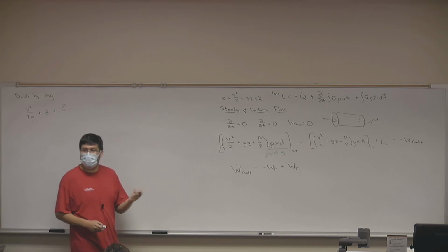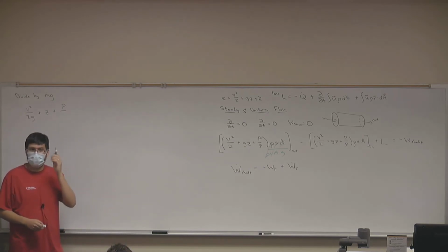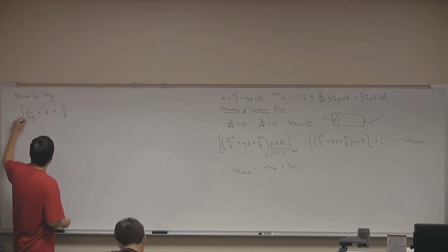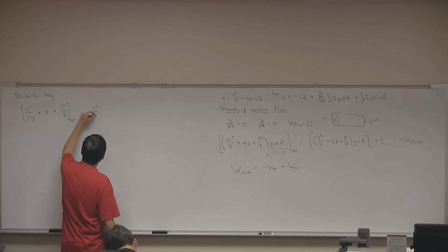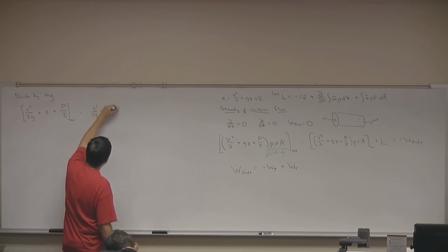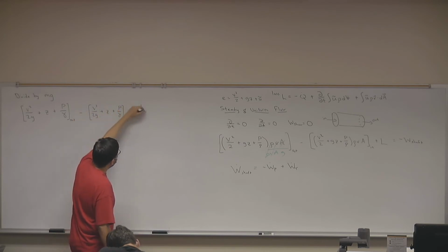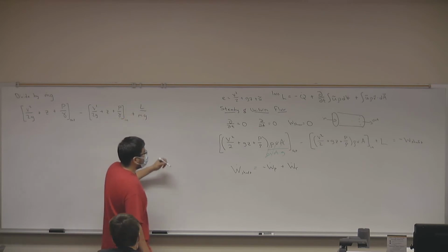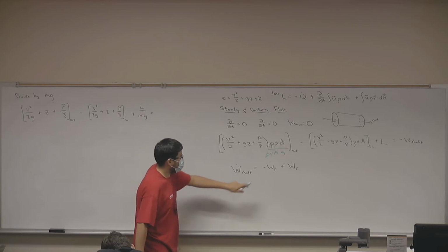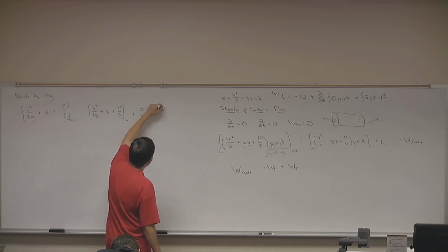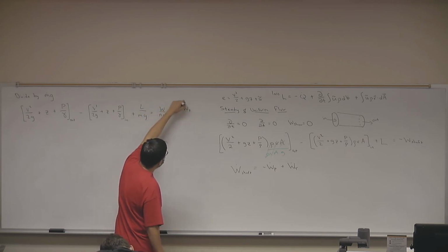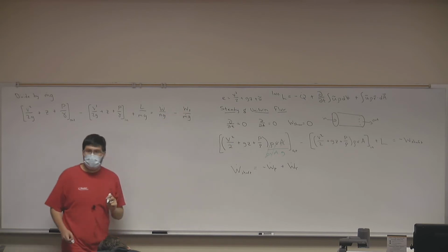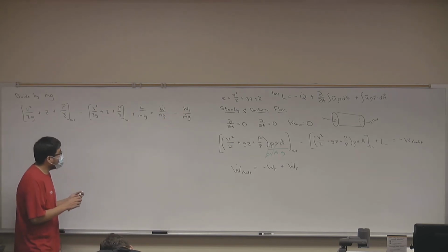What's density times gravity? Specific weight. Good. So we have all these energy terms leaving the system minus the same terms entering the system, plus my losses over mass flux times gravity, equals my pump power divided by mass flux times gravity, minus my turbine power divided by mass flux times gravity. Okay, good. We're getting somewhere.